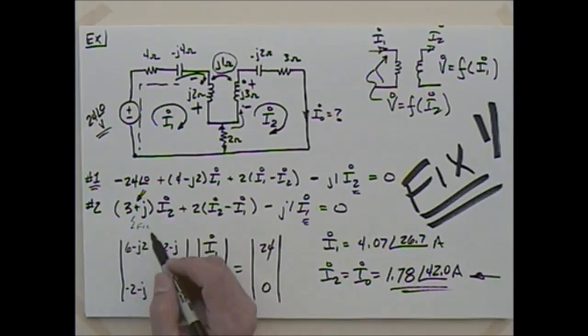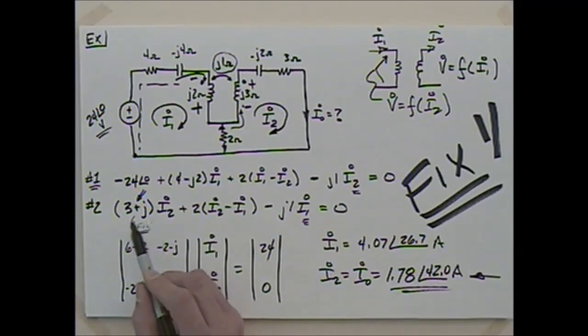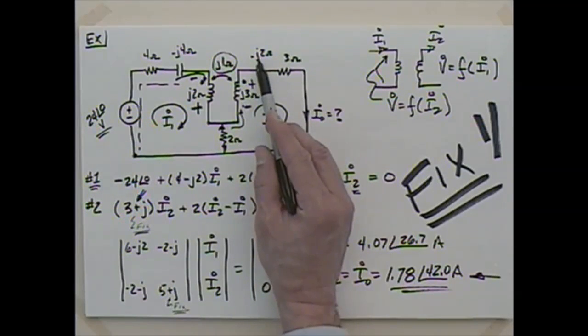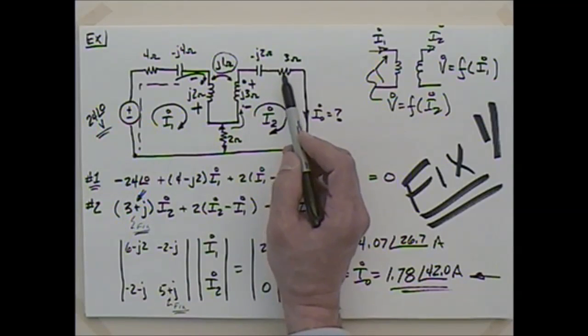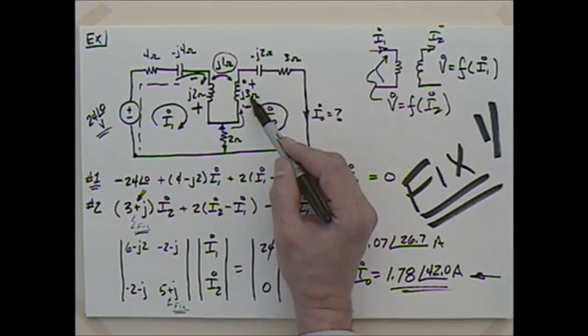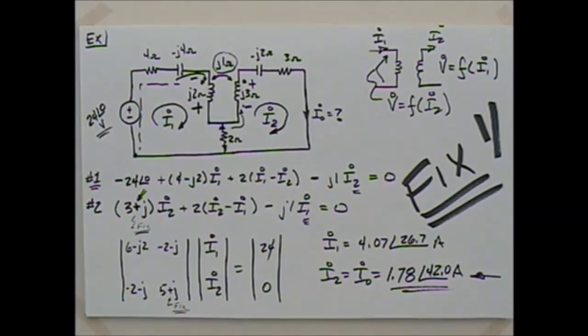Okay. So the problem here, and again I noted it on the PDF with a light highlighted fix, but I wanted to talk about it so that we could at least get it recorded that we've corrected this. So going around this one, I have J3 minus J2 and then 3. So I had initially written 3 and then minus J. Well, it really should be a plus J, shouldn't it? Because I've got positive 3 and minus 2 should give me a plus J. So make sure that your notes, and when you see the video, you get that correct in your mind. That should be a positive J there, I2.